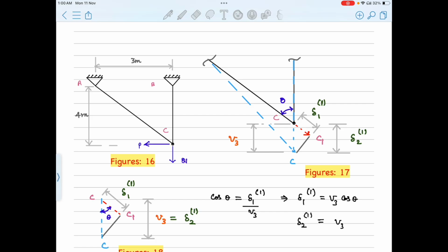So we are just going to take this at once, then later we will consider U3. Okay. So out of the overall displacements resulting due to the loads applied at joint C, we are taking only V3 into consideration first. Mind that this V3 is a global degree of freedom. Now for compatibility, the local degrees of freedom delta 1 and delta 2 must be such that they meet the geometric requirement involving V3 so that each member's ends move to this new location C in unison.